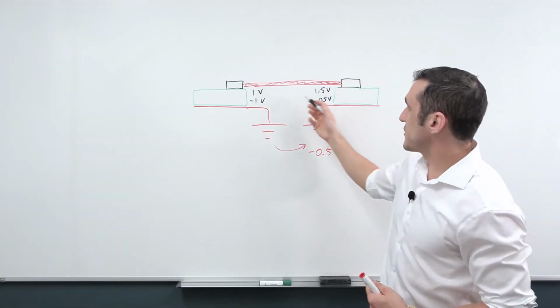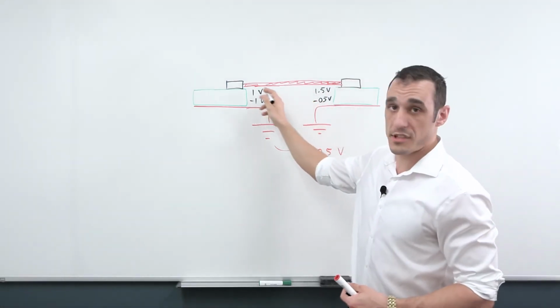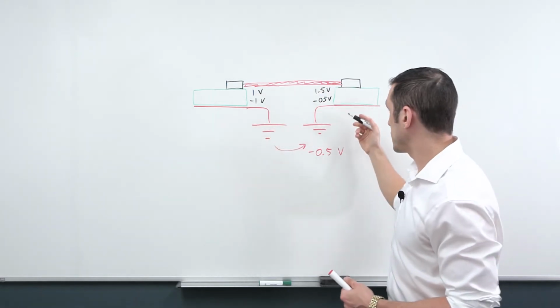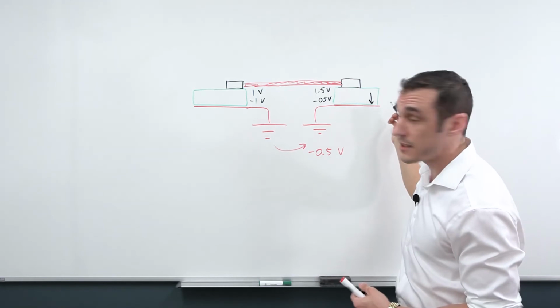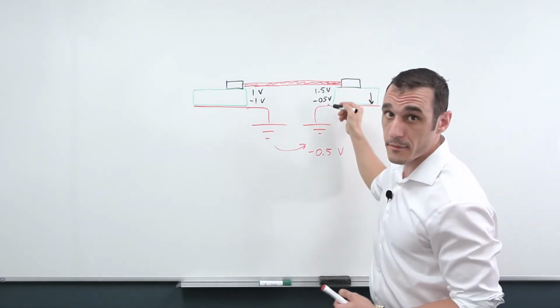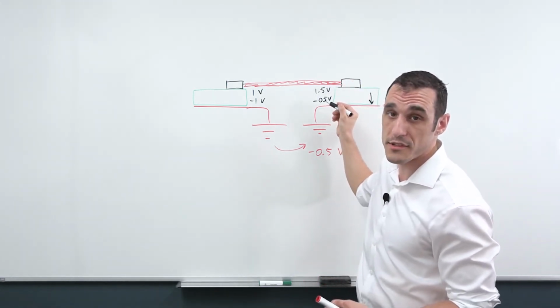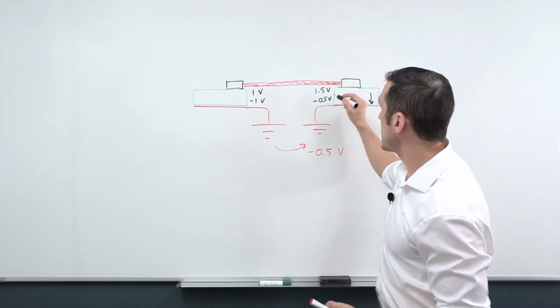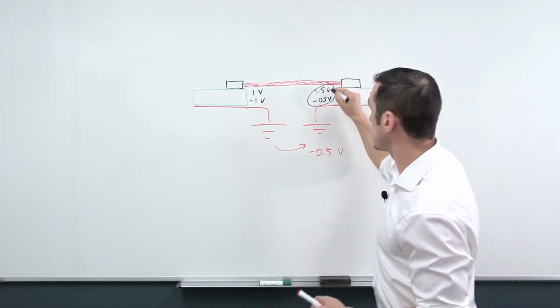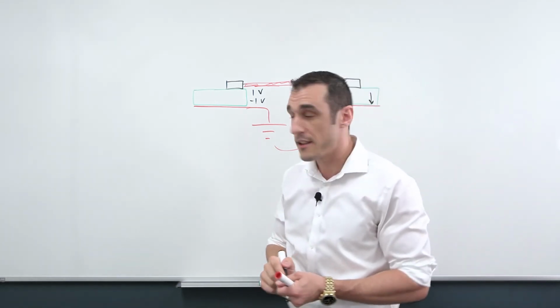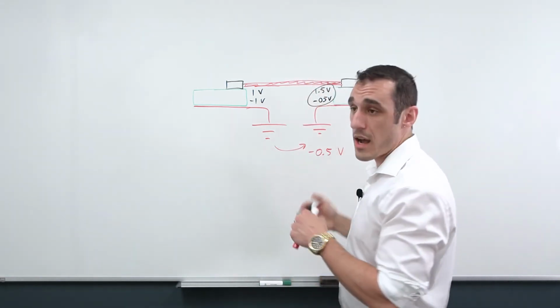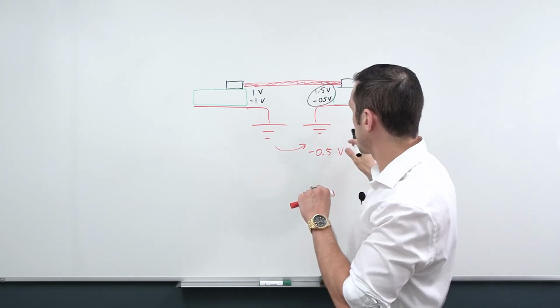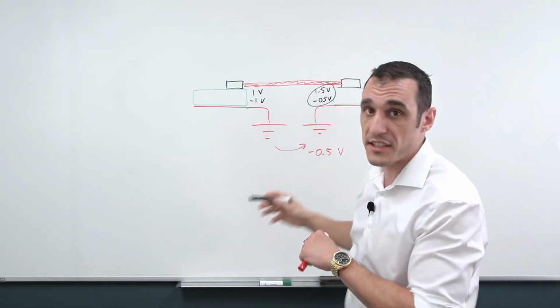So even in this case where each of the individual signals has a different voltage measured with respect to this ground on this PCB, the voltage between them has been maintained at 2 volts. And so that's what's really key here, is it's the difference between these two voltages that's being used to communicate a digital signal across this link. And that's why you have a great advantage with differential pairs, because this ground offset doesn't even matter.